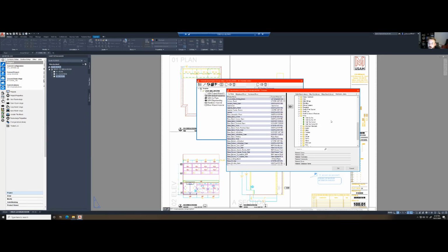And so for hardware in particular, a lot of times we just need things to come out on reports to tell people what to pick. So instead of actually having to create formula driven hardware, we just add formula driven hardware in our products themselves. And if you don't need machining or any drawings or things attached to that, you just need it for reporting purposes, it'll do everything you need.